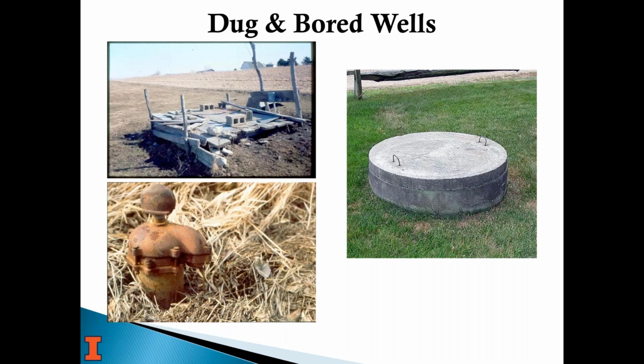And what that means, though, is this is a 4 foot section of concrete tile, and it's sticking up a foot above land surface. So the first joint is down at 3 feet below land surface. That's not necessarily protective. Water's going to seep in. If they have a nice yard there with no weeds, they're spraying, maybe fertilizing, all that stuff, it gives that an avenue if they haven't done anything to protect it from having water seep in that shallow.